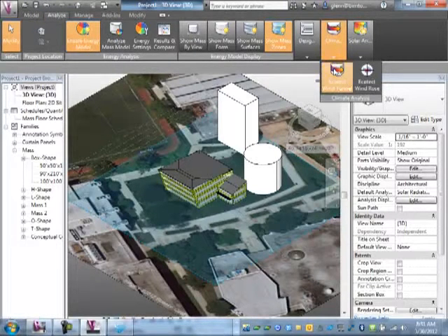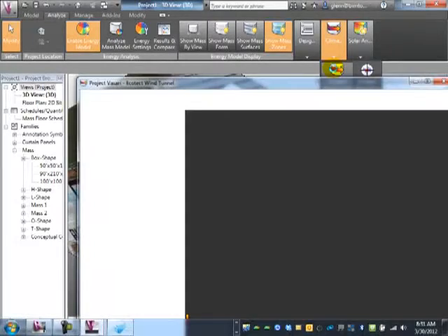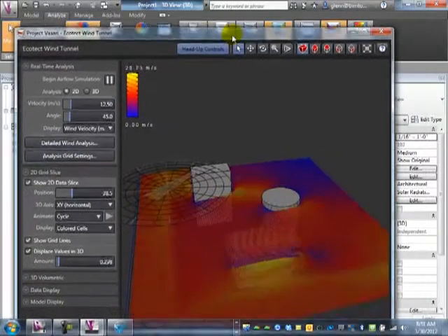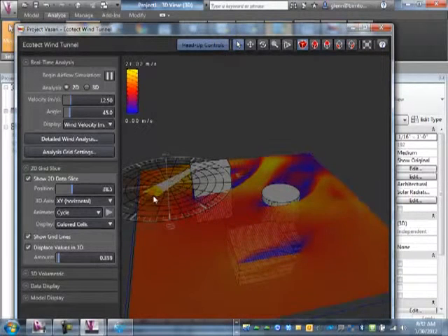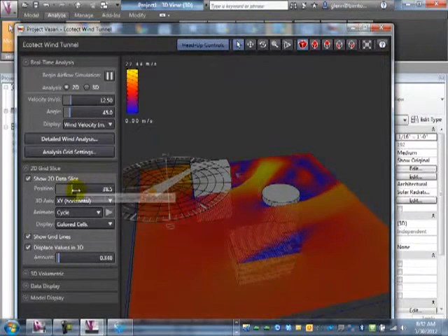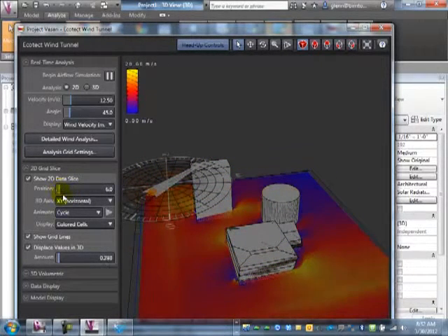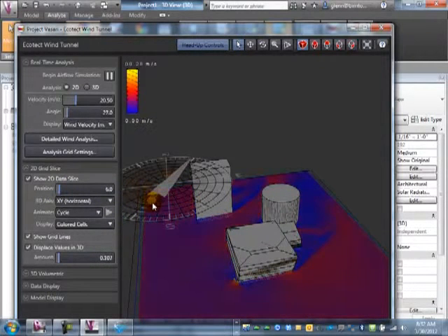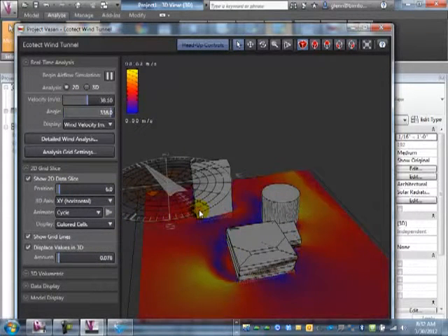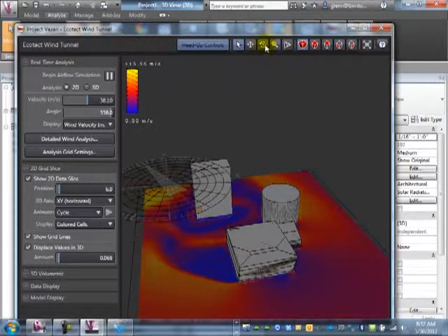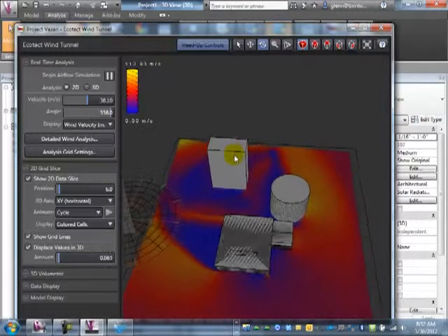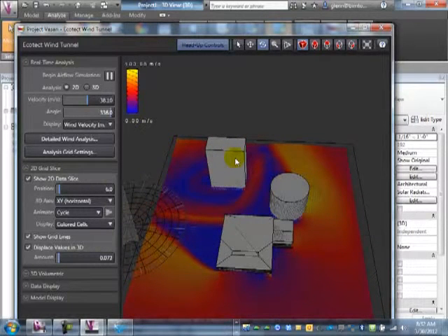Let me show you in here. There's this whole thing about the wind tunnel. This is all about, if you're interested in doing wind analysis, there's a wind rose over here. And the wind data in the rose over there actually is accurate for Newark. So we can do things like see what's happening to the wind speed as we move around and change the wind intensity in different directions. And you can start to see what the effect of the wind around your various buildings is. See where you start having shedding problems or vortex problems, where you have dead spaces. If you're trying to plan some sort of naturally ventilated thing, figure out where you're blocking the wind.